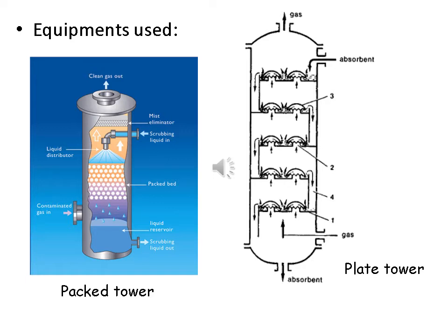The working principle of this packed tower: liquid enters from the top of the tower and is evenly distributed onto tower packings through a liquid distributor. The gas enters from the tower bottom and is distributed evenly through a gas distributor device.